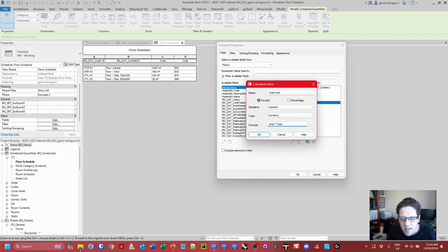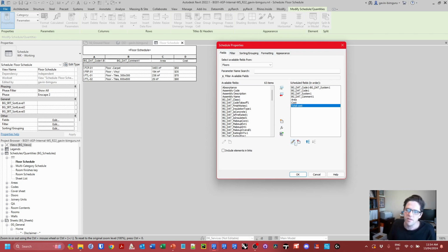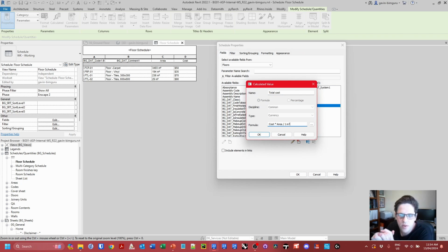Okay, I've got an inconsistent unit, so that's interesting. I mean, it should definitely at least be able to support cost. Might have to divide it by 1. Yeah, okay, so sometimes if you have a unit-based field and you need to turn it into a number, you need to at least divide it by 1 of its own unit. By default, Revit will let you divide, and then it sorts out the unit for you. So you can see what happened there is it divided by 1, and then it went, oh, you're an area. Divide the unit out. So in this case, it's divided it by 1 meter squared. Just a bit of a little workaround there.